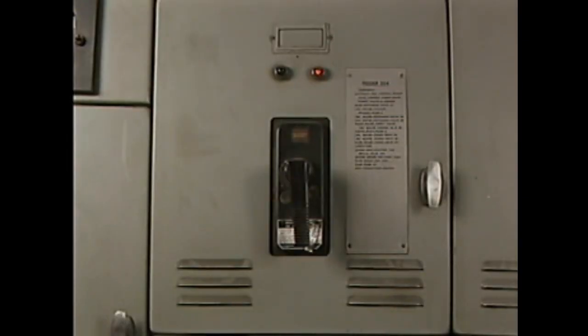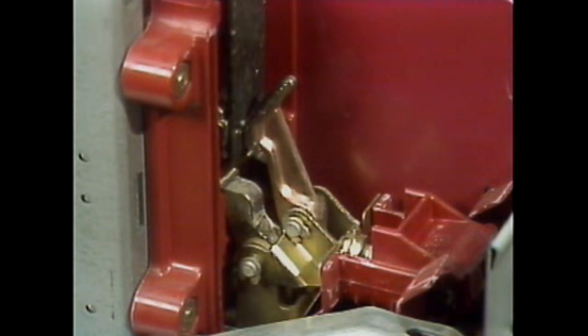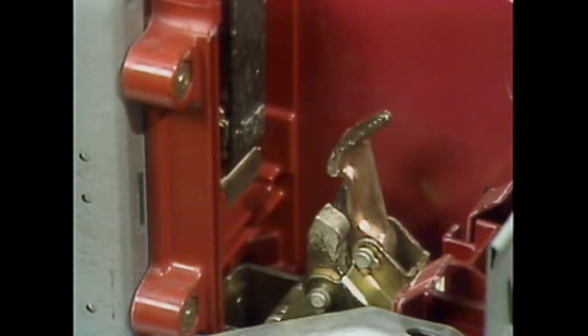One type of component that's found throughout a plant's electrical distribution system is a circuit breaker. Circuit breakers serve as protective devices, and they also provide a way to isolate electrical equipment from a source of power. When it functions as a protective device, a circuit breaker helps prevent excessive current from damaging circuits and equipment. A circuit breaker is able to do this because it has electrical contacts that open or trip to interrupt current flow to a circuit.